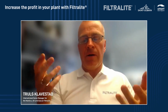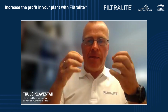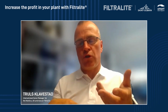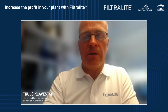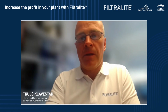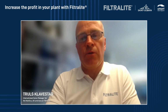Very often, if you have a depth of, for example, 1 meter, you are not able to use the full depth, because of how sand particles look, you're using just the upper part of the filter, and then you need to stop and backwash. So that is the disadvantage of using sand compared to Filtralite, especially with algae. We probably have some peaks during the year, and then Filtralite is absolutely a perfect solution to solve that kind of problem.